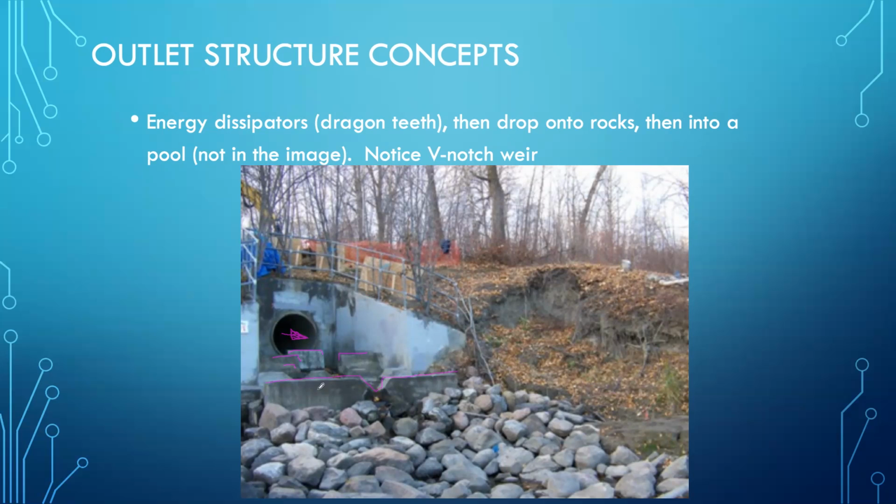The weir, I suspect, was actually for flow measuring. And let's see if I can see the bubbler pipe to measure flow, but I can't see it, but you wouldn't necessarily put a weir there just for show. We have these wing walls, which are made out of concrete, and that should have worked.